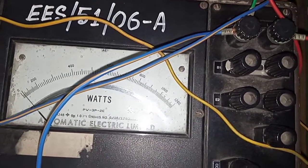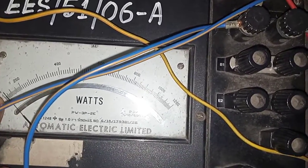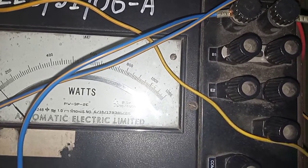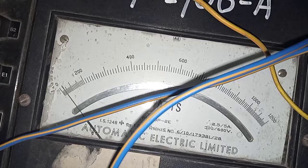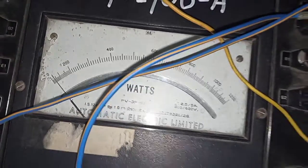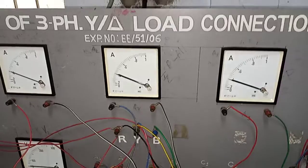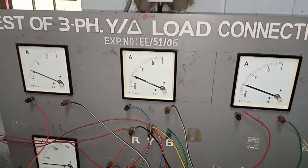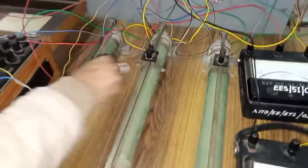In that case, if we see this scale is 50, then it is around 1, 2, 3, less than the fourth scale, that means less than 40, around 37, 38 we can assume. So if we assume 37, 38, then correspondingly into 2, that means 76 watt. Previously when we showed 0.9 ampere current, that time also voltage was remaining the same. Let us go to that position once more, because we will have to see the wattmeter reading that time also. You see, I am changing the resistance.